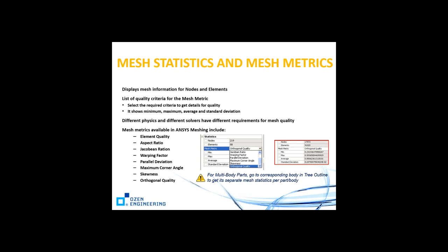If the aspect ratio becomes more than 10, then in FEA you're almost guaranteed to get bad results. And in CFD too, if that stretched element is in a field where there are tangential or normal components of velocity, you're going to get bad results in that location as well.